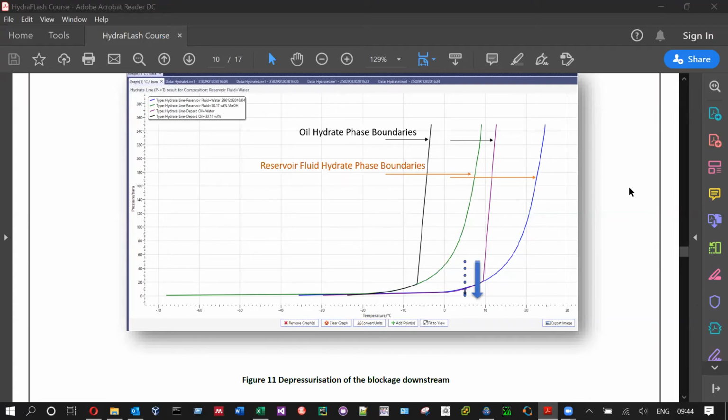And then they assume a percentage of inhibitor they add because of bad distribution. Now, the fact that they inject methanol at the wellhead, the wellhead temperature is much higher than the hydrate stability zone. So hydrate is not forming.